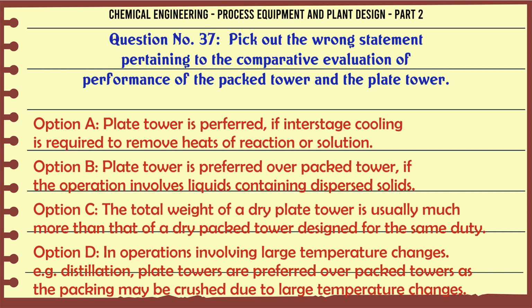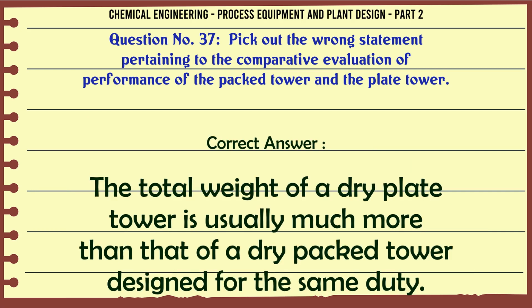C. The total weight of a dry plate tower is usually much more than that of a dry packed tower designed for the same duty. D. In operations involving large temperature changes, e.g. distillation, plate towers are preferred over packed towers as the packing may be crushed due to large temperature changes. The correct answer is the total weight of a dry plate tower is usually much more than that of a dry packed tower designed for the same duty.